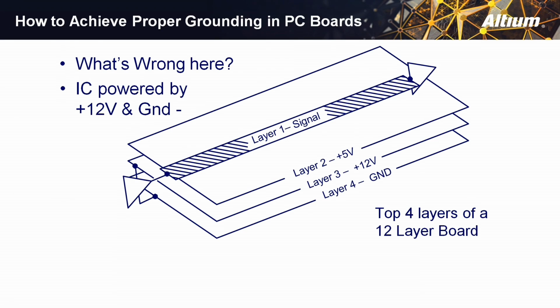It's coupling into digital circuitry, which just happens to have harmonic frequencies up near a gigahertz, which is where the signal was functioning. That harmonic energy near a gigahertz was corrupting the signal when it was at a low enough level. There was enough energy in the high frequency harmonics to cause this thing to malfunction.